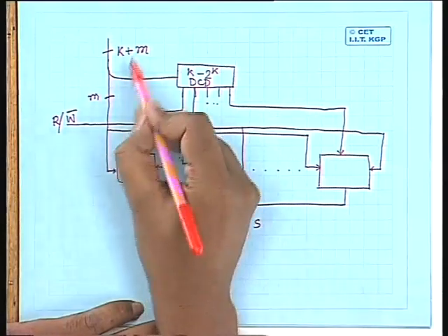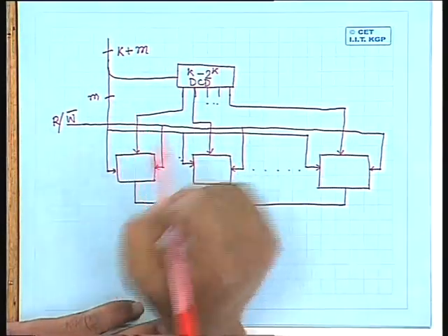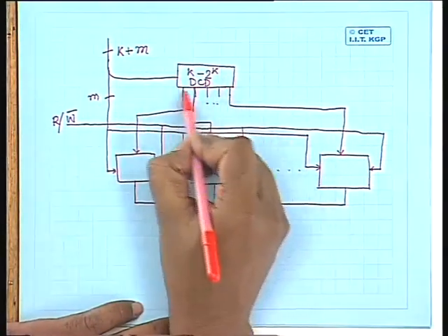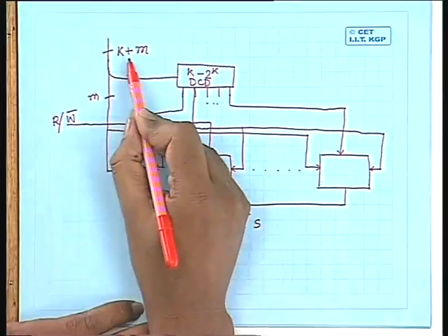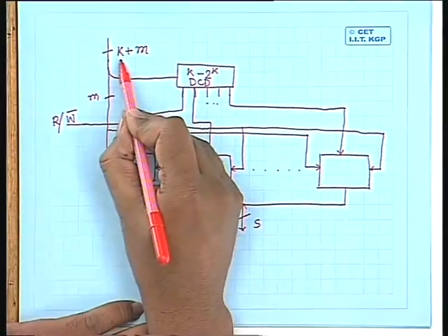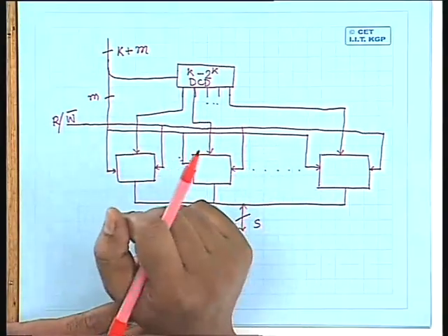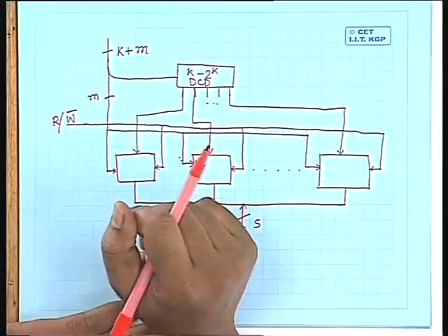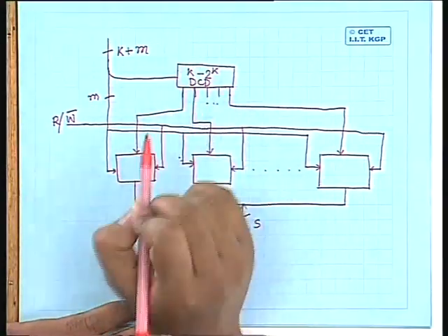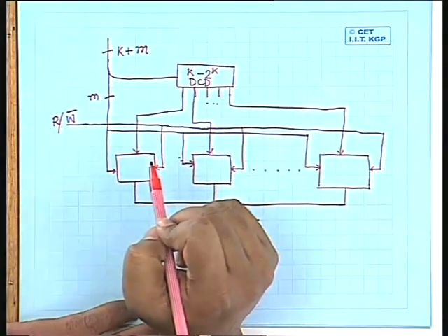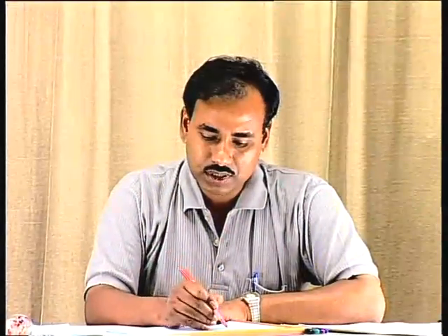So if the value of K is quite large, to reduce this decoder complexity what we can do is break this value of K, the number of bits, again into two components. For each component I will use one such decoder. Both the decoders will give you some outputs, and these outputs will now be used to activate the chips.